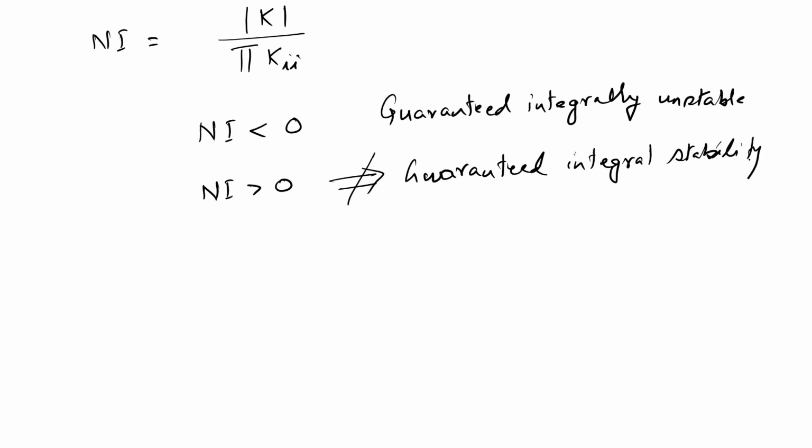Why is that? Because even in a single loop system you can always mess up the tuning and get instability. In a multivariable system, you have that additional figure of 8 interaction, so stability is not guaranteed.